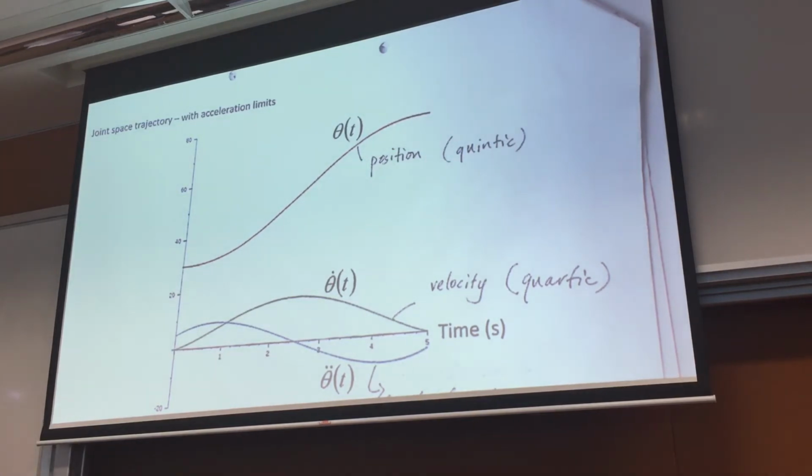And actually through here, what I want you to see is a few features, especially for acceleration, because in the next class you get to hear about acceleration. Whenever you have a discontinuity in your acceleration profile, you'll see that next lesson. Over here there's no discontinuity, it's a very smooth cubic line. If you have discontinuity, you experience jerk. And this jerk is bad for your robotic device, because your motor will experience that jerk. So as much as we can, we try to avoid that.